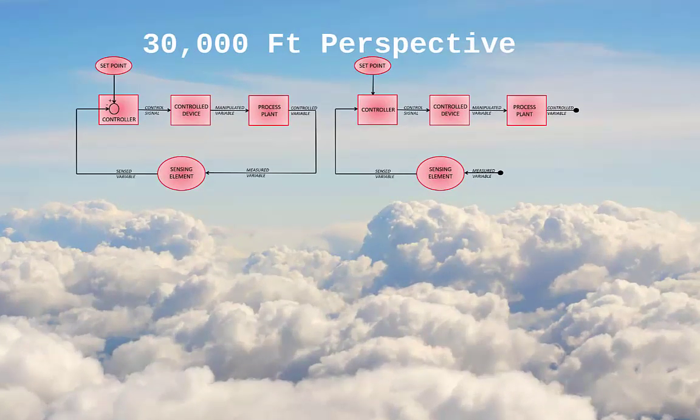What are sensors used for? As I just stated, the sensor is a component of the control loop. It doesn't matter if that control loop is an open or closed loop. Both types would contain a sensor. Sensors located in the control loop need to not only be able to measure the property they are looking at, for example, the temperature of an airstream or the pressure in a hydronic system, but they also need to transmit that information back to the controller.